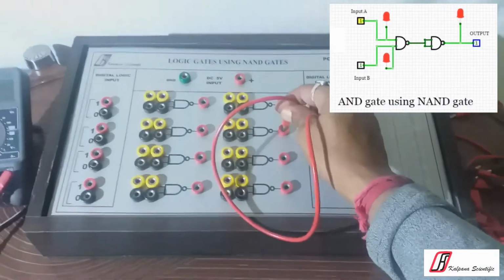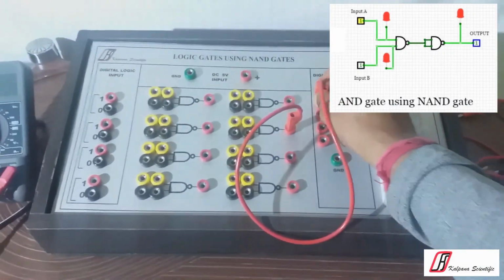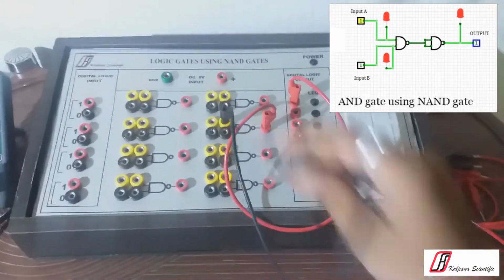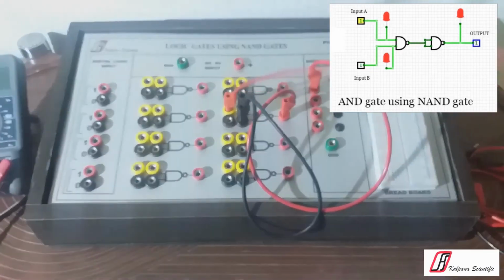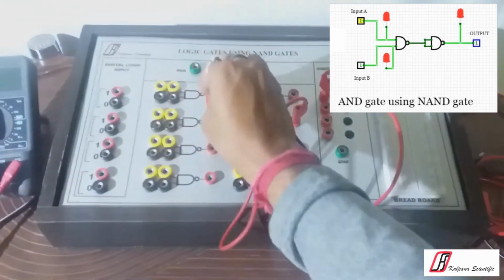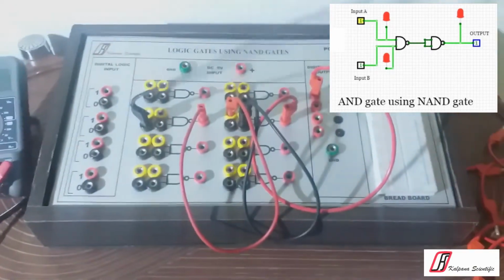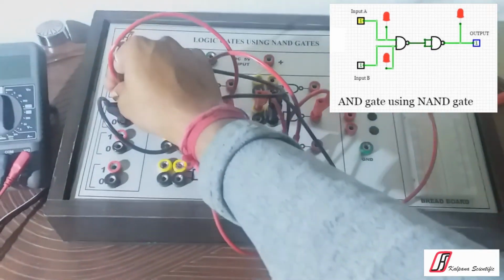Let's construct AND gate using two NAND gates. Connect output of a NAND gate to the output LED indicator. Connect the two inputs of same NAND gate with each other by patch cord. Connect this point to output of another NAND gate. Now connect the input of this second NAND gate to logic low terminal.